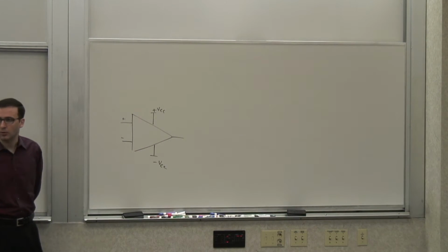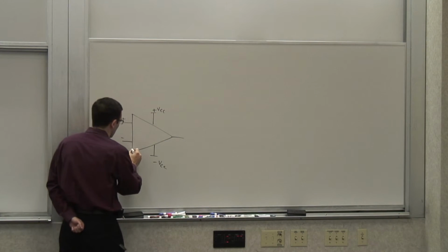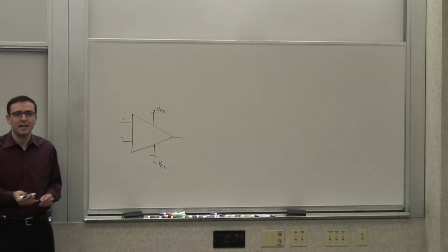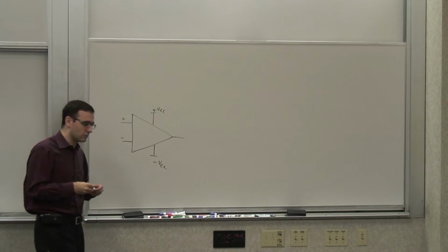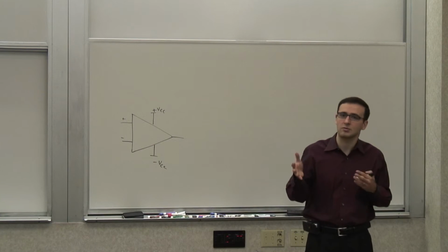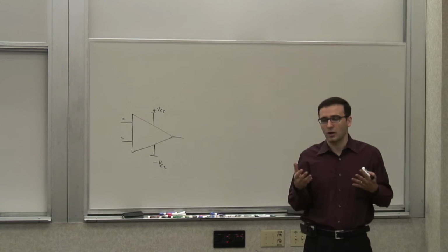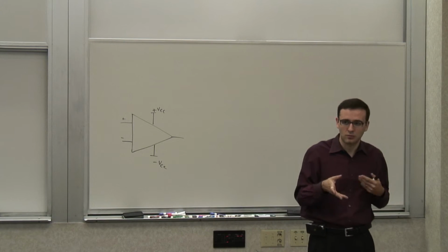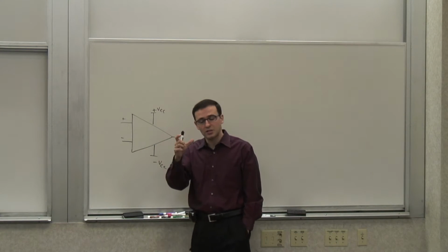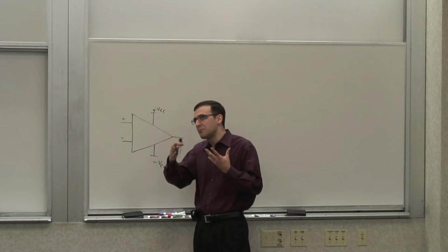Let's first do it in bipolar. Right? And so let's say we have access to a bipolar technology, which gives you basically a standard bipolar technology, which gives you reasonably good NPNs and okay PNPs. The PNPs are not that good in terms of the gain bandwidth product, it's not as high as the NPNs, so we try to get the gain stages to be mostly NPN if you can.